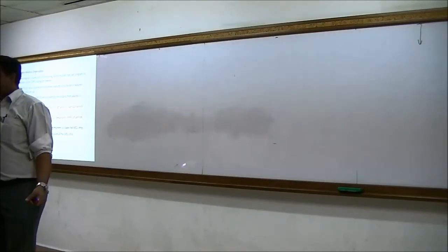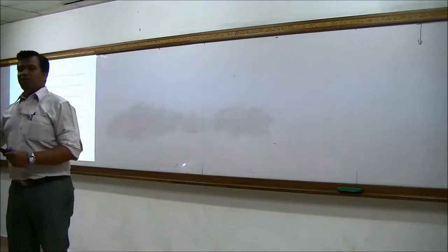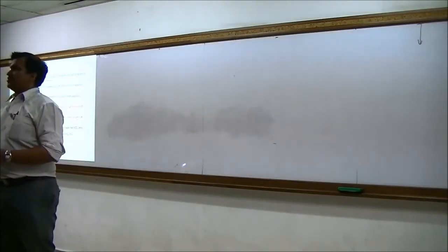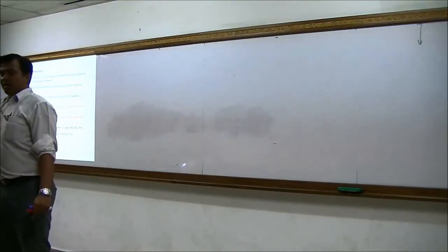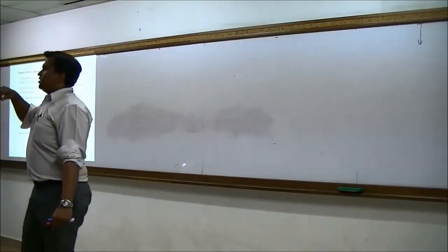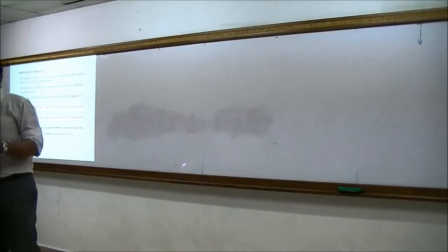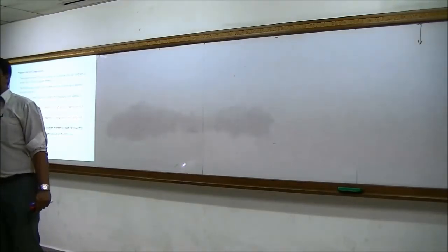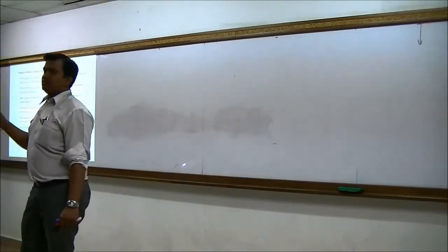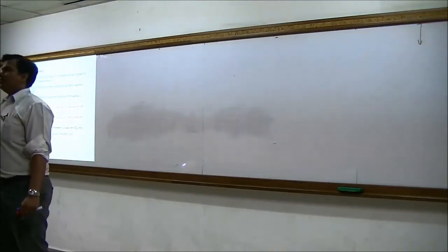What happened? 21 bits, right? So what we did in the previous class is we derived the range of the program memory address. When n equals 21, in binary we wrote the first address as all zeros, and the last one will be all ones. We don't always represent it in binary because a binary address is too long. So we use the compact representation, which is hex. We get hex 000000, and the maximum is hex 1FFFFF.